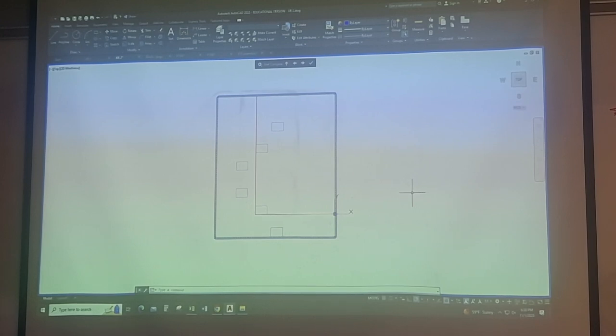The beauty of that is that when your supervisor or whoever's over that project that you're working on, you might have 100 drafters in there working on drawing pipes up for a project. That supervisor or superintendent doesn't have to stand at the door with a box of thumb drives saying, here, that footprint changed. Put this in your computer and use this now. Here's yours to everybody that comes in. And then have to go around and check and say, all right, did you use that? Did you use the new version? Let me see it on your screen. He doesn't have to go through there and check that. By doing that, that can make it accessible to the whole drafting department.